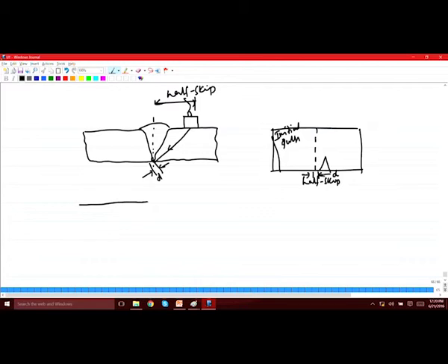So, this is how, in case of weld inspection by angle beam probes, the reference will be the half skip. Let us say, for example, if you have a defect, some kind of root cut or lack of fusion, due to which there is some improper fusion between the plates, and at the root there is an opening like this. So, in that case, if you keep your probe again at the half skip, even before it goes to the root, it will encounter this defect, because there is now an opening.